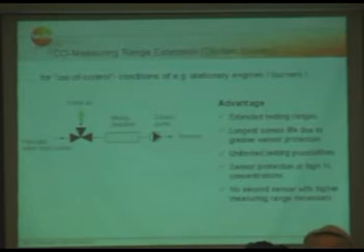Some competitors provide a low range sensor, a mid range sensor and a high range sensor for CO, NO, and according to your application you have to choose the right sensor. But that means if you have two different applications where you have high readings or low readings, you have to have two sensors within the same instrument, which has an influence on the costs, of course.